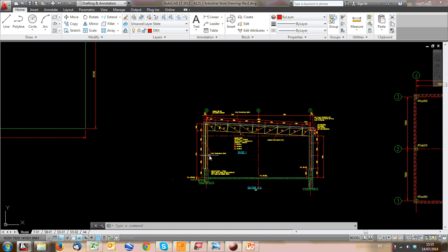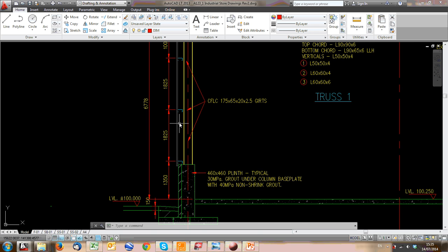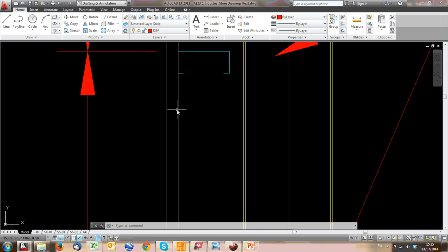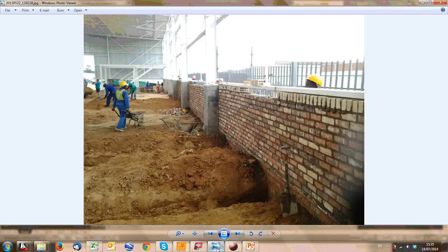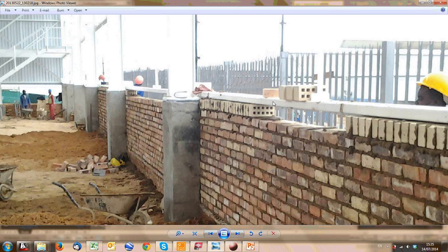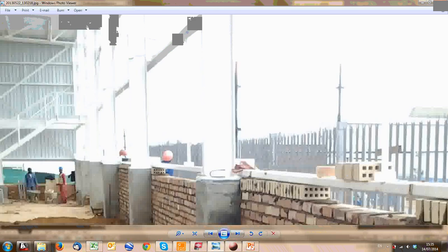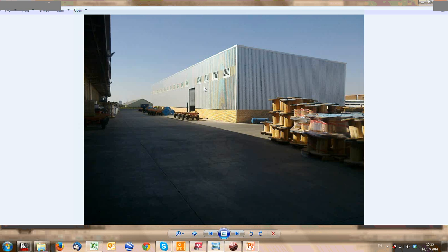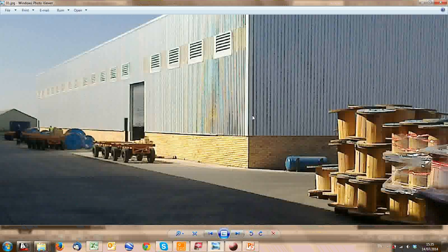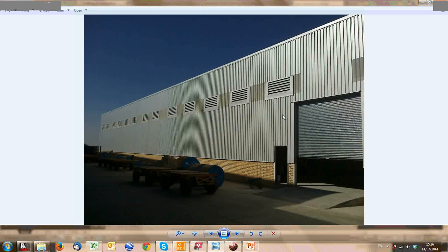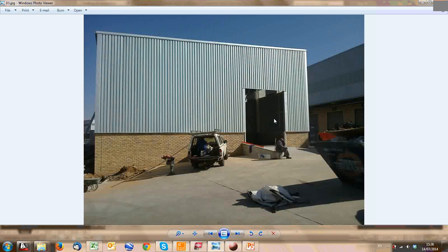But let's say in this case, you've only been given a sheeting line, and the sheeting line is to the inside sheet. That is here. I'm going to go find a picture of that. In this building, the sheeting line would be the edge, the outside face of this girt, and the girt is sort of a cold formed lip channel steel section which you can screw sheeting to. That would be your sheeting line there to the edge of that piece. The sheeting line would be to the inner face, the inner flute of this sheeting here.